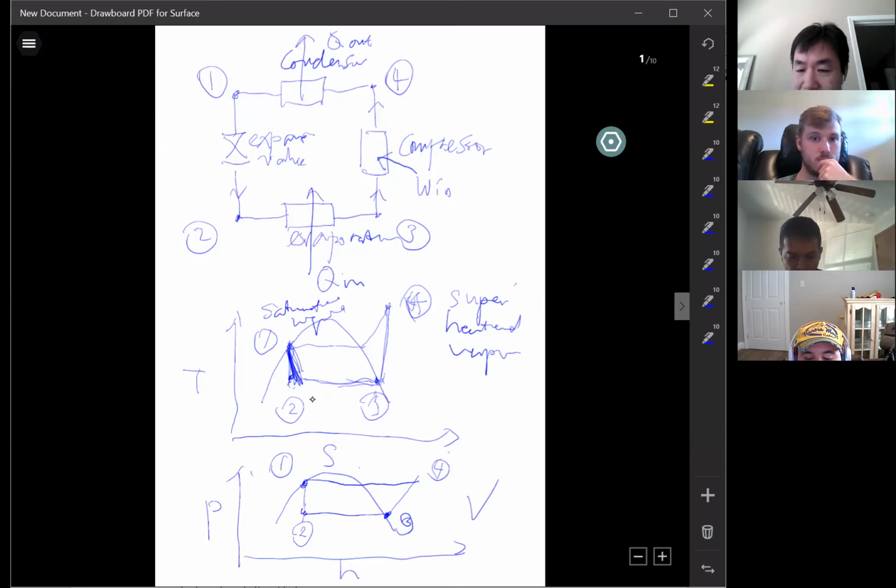Okay, the drawing here is the ideal situation. Ideally, after going through the evaporator, the point is on the saturated line. But in reality, when you do the measurement, you will find that it's not exactly on the line. It's a little bit inside. Actually, they have a dryer in the unit system too. So when you measure the point at the compressor inlet, it's actually inside the vapor region. The actual point from your measurement, point 3, is inside the vapor region. So I want you to calculate the degree of superheat at point 3, at the compressor inlet.